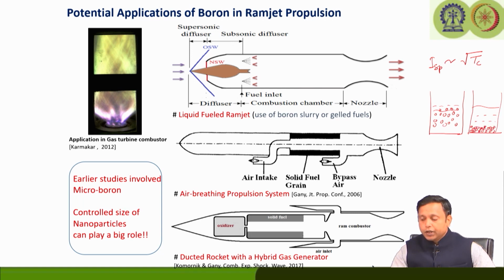So, how do we suspend these particles for a longer period of time for use in the engine application? That is why gelled fuel is another approach, because a gel has the capability to act just like a solid when it is not being stirred or pressurized, but it is going to act as a liquid under shear.